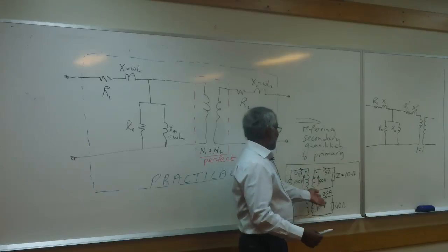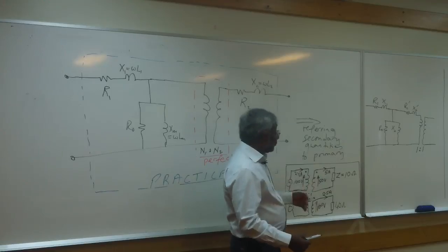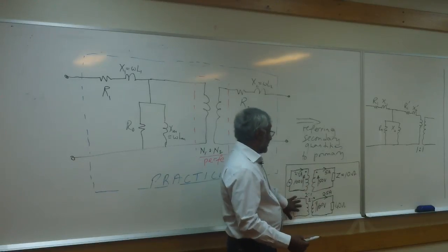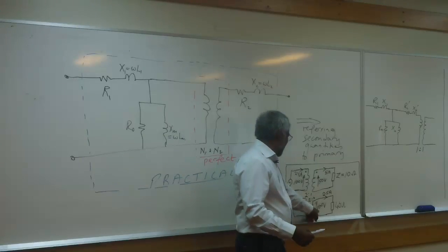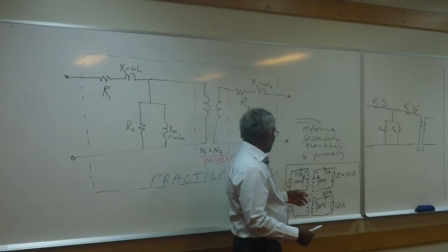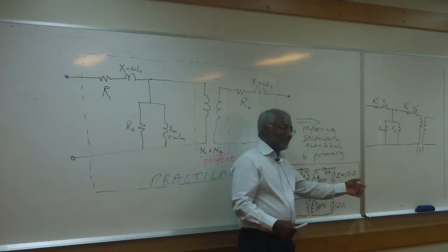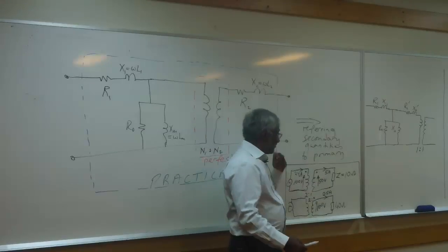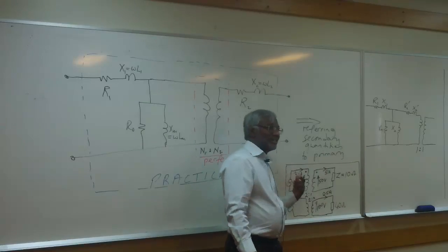You can think of other equivalents. You can think of, instead of making it 2 to 2, I could make it 2 to 4. Primary side doesn't feel anything. For that to happen, if it was 2 to 4, that would become 200 volts, and this will become 1.25 amps, and this will become whatever it is that you can calculate. So you can see the primary side doesn't care what you put on the secondary side. You can change it without it knowing anything.